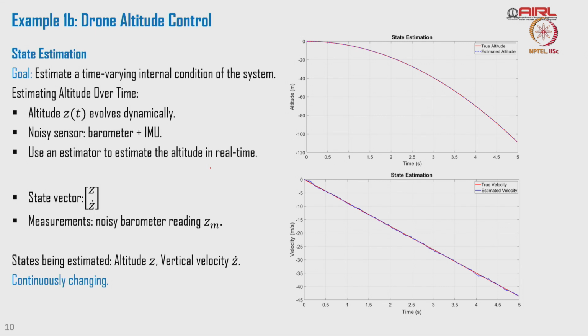If we talk about soft landing, what does it mean? The velocity at which you are coming down should decrease with respect to time. When you touch the surface, velocity should be equal to 0, closer to the surface. Now, the other constraint will come, can height be negative? What does it mean? You have impacted the ground already, right. So, height cannot be negative. When height comes closer to some epsilon, I will cut off the motor so that the drone touches the ground with minimum impact, right. So, you need to estimate these two if you want to do precision control of altitude.